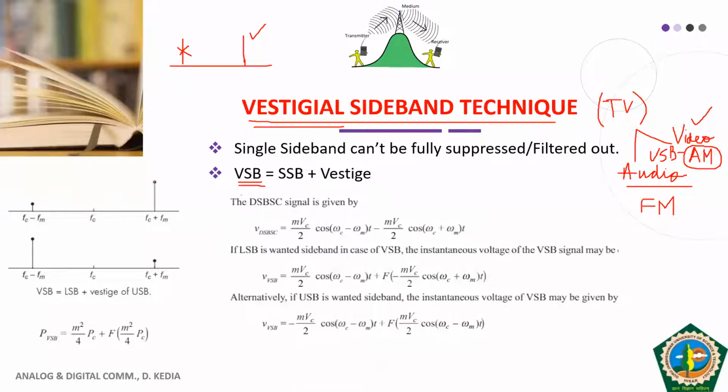Say this is the upper sideband, so we keep the upper sideband complete, and the lower sideband we do not keep complete, but only a part of it. This part is called the vestige, and that's why the name of this technique is vestigial sideband. So in vestigial sideband, we have a single sideband complete plus part of another sideband.